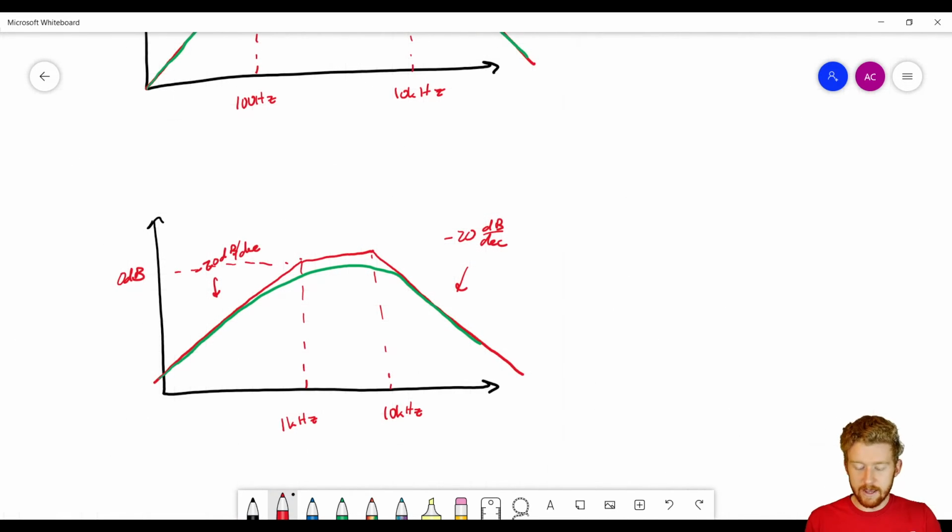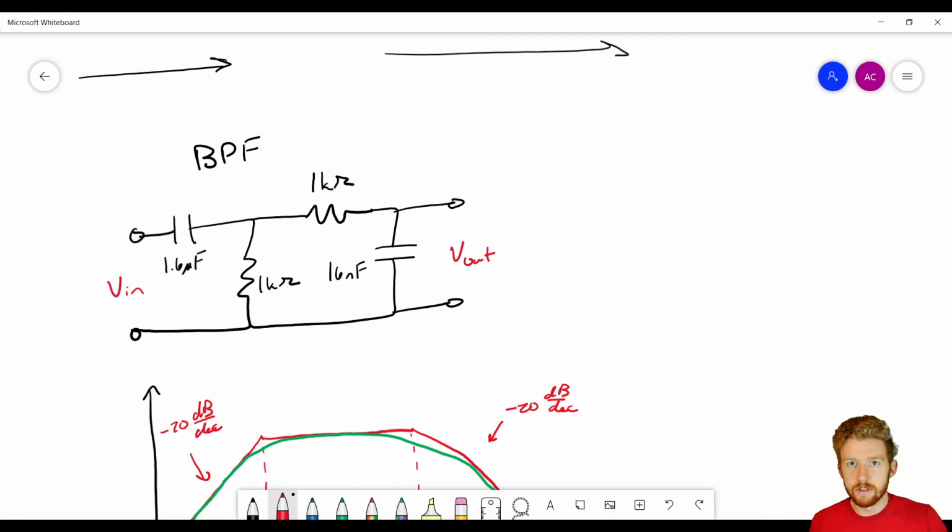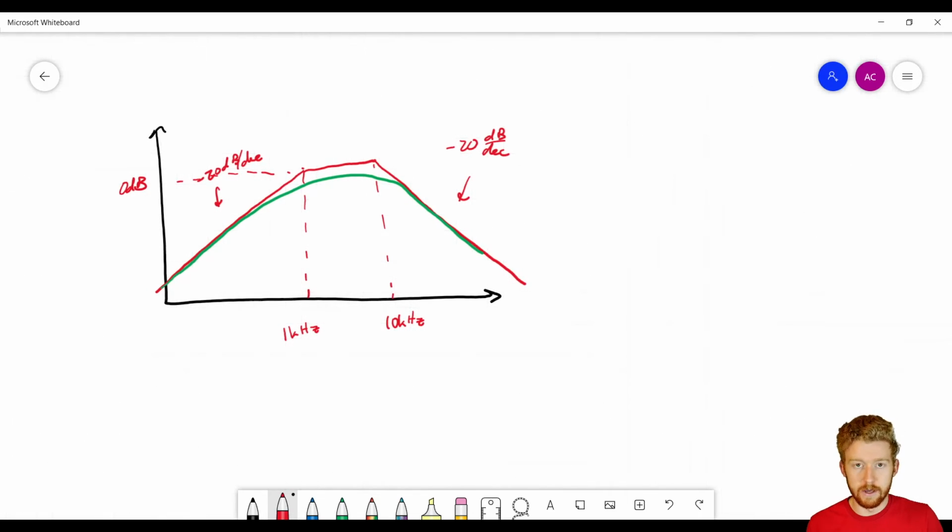But whenever those two cutoff frequencies get closer and closer together, you're going to start having more and more interaction between the two. Originally we just said, let's connect two filters in series, bada bing, bada boom, and we end up with this idealized response. But if you move those two cutoff frequencies too close together, you're going to start having more complex interactions, and we're not going to be able to think of it in a simplified manner. So this is something you have to be aware of.